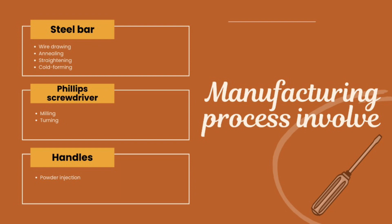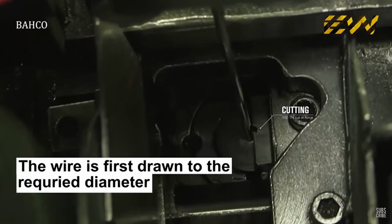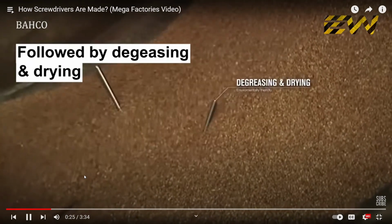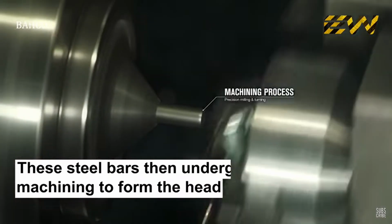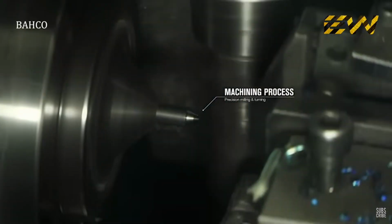The screwdriver is sent to a switch and grind operation, where dies form blades for a tip from the heated wire. The tool is then ground and the wings are formed. If a professional model is being produced, the bar goes to a tipping operation, which is an automatic tipping machine